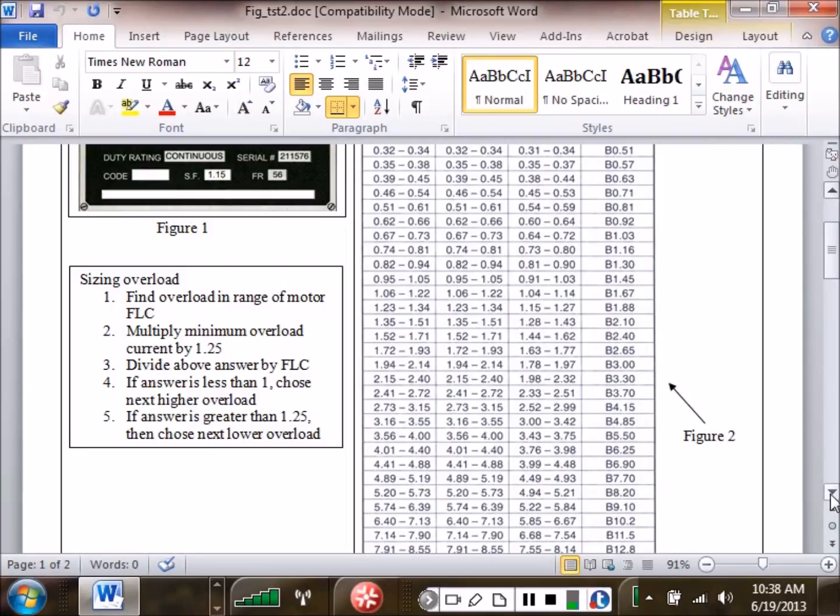A single voltage motor, 90% of the time, I'm not going to say you're not going to run into one that's got external overloads. But on a single voltage motor, the overloads are usually inside. And some of them have a little reset button on them, so you reset the overload. A lot of your smaller motors, the overload is automatically reset. Like a hairdryer. Your hairdryer has an overload on it. If you stop up the back so air can't get through and cool it off, eventually your hairdryer will kick off. But if you let it cool off for a little while, it should come back on because it's got an auto reset overload in it.